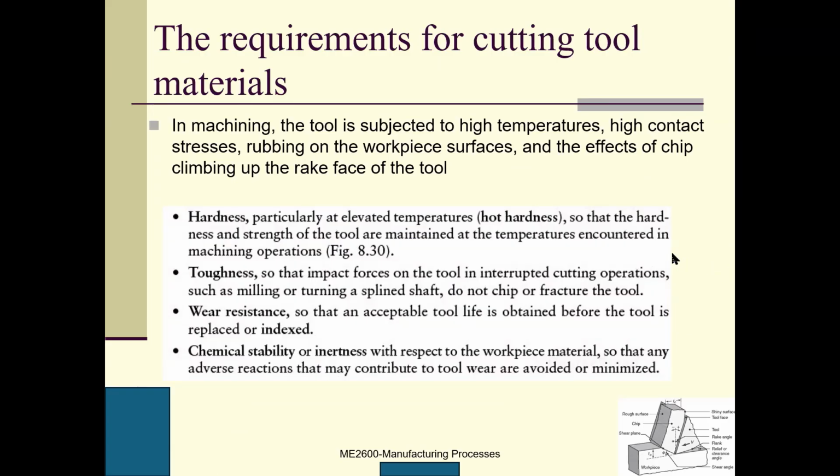And here are the requirements for the cutting tool materials. First, we know that the tool is subjected to very, very high temperature, very, very high contact stress, rubbing on the workpiece surface, and the effects of the chip climbing up the tool. So this is the tool. Whenever you think about the characteristics of the tool, you need to put yourself in the shoes of the tool and think, what kind of conditions will my tool be encountering? Okay, so then you can just imagine.